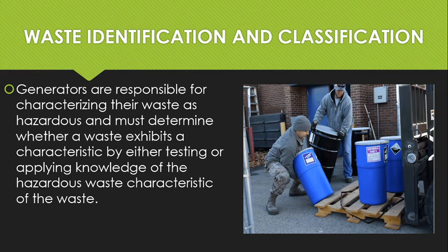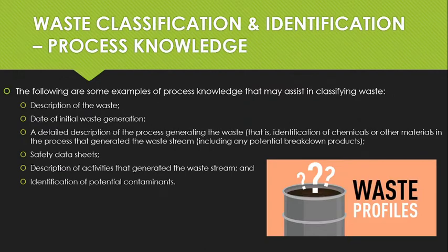So first of all, waste identification and classification. Generators are responsible for characterizing their waste as hazardous, and they must determine whether a waste exhibits a characteristic by either testing it or applying knowledge of the hazardous waste characteristics of the waste. So basically testing versus process knowledge, and we'll go through what those are specifically.